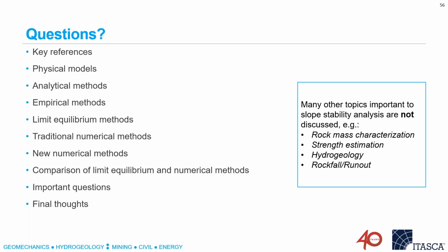And two fundamentally different approaches. They can be modeled as explicit interfaces in something like FLAC3D or 3DEC. So these are surfaces which have no thickness, but they can have slip and separation. And that's probably the way to best represent most faults. But some faults are really fault zones. They have a thickness to them that may be 5, 10, 15, 20 meters thick. And there we might want to include them more as a material model.